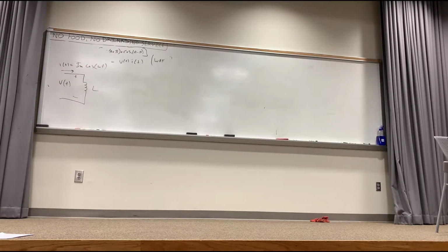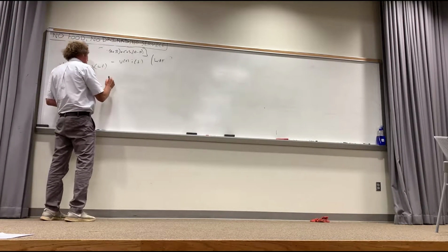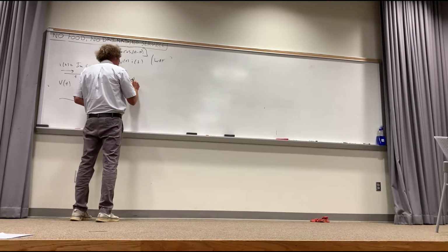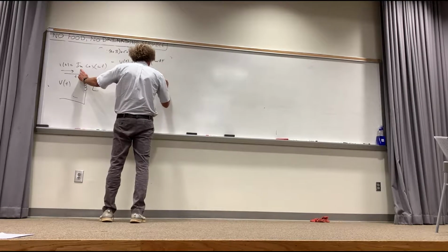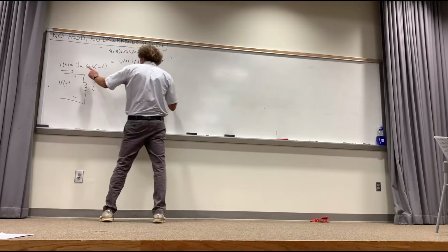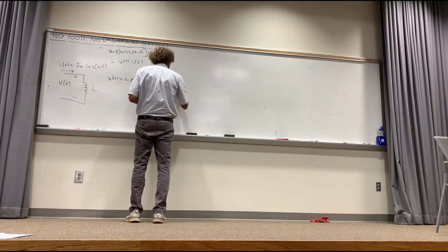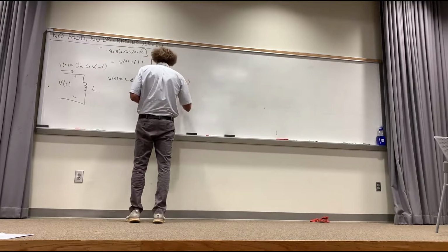All right, so for this thing with the inductor, that's going to be the current, therefore the voltage v(t) is equal to L times di/dt, right? And that means it's going to be minus L omega Im times sine of omega t.